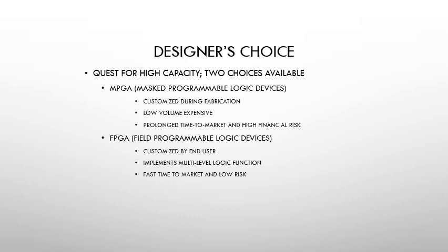FPGA means field programmable gate array. This device has some features that are different from MPGA. These are all customized by the end user, it implements multi-level logic functions, with fast time to market and low risk. So the designer's choice is available in two high capacity options, MPGA and FPGA.